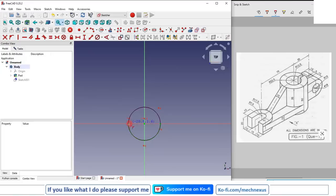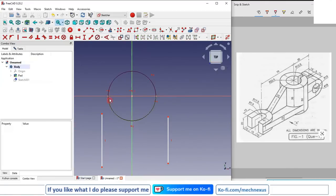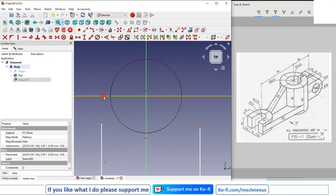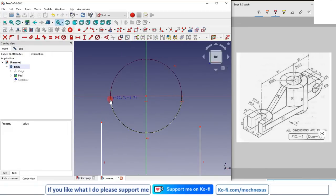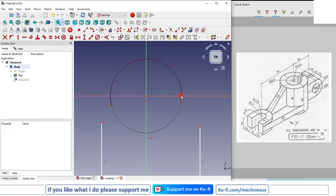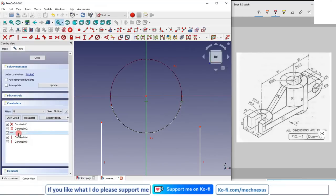So I will select the line. I will draw the 2 line, make it vertical, and I think this horizontal constraint we should delete it, because we do not know where it will come. So if you are facing the difficulty, go to the task, and this is that horizontal constraint, say delete.